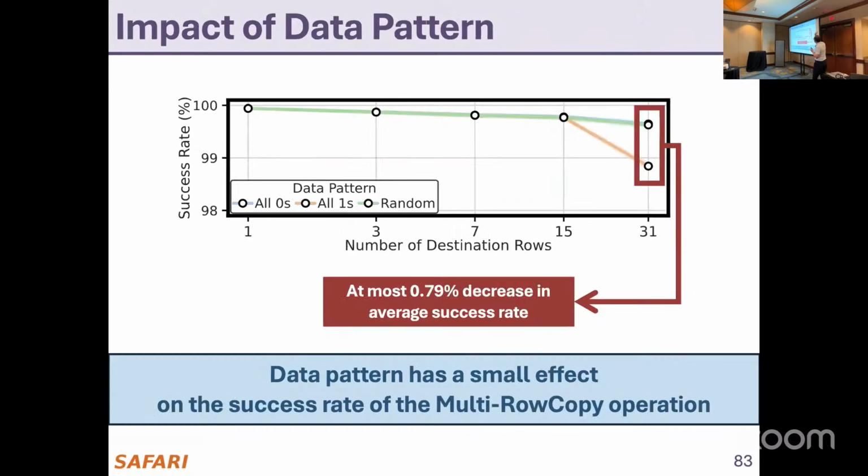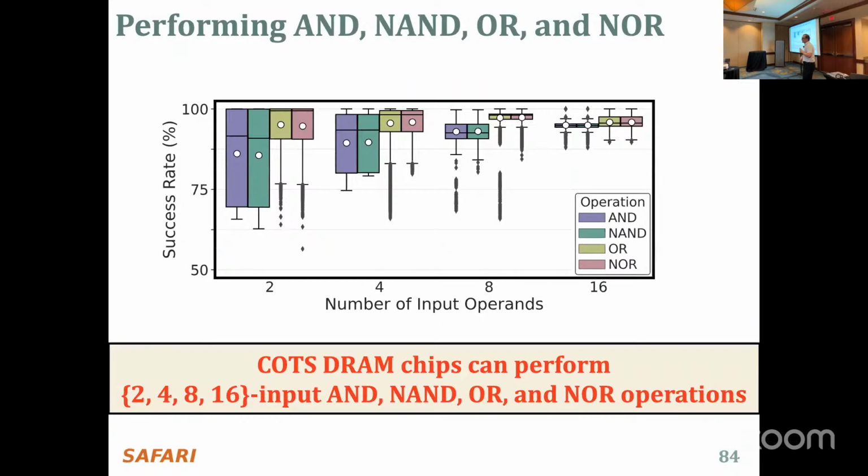I'm going to skip some of these things, but you need to also vary the temperature, voltage, and data pattern to see the sensitivity of this operation to different variables clearly.